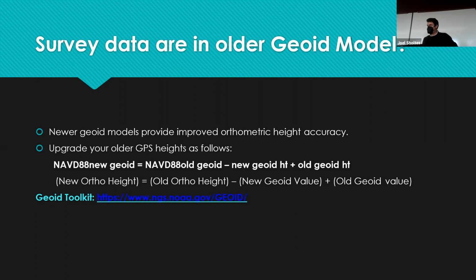There's a vertical datum, basically it's tied to mean sea level in Newfoundland. You remember that? And then they took that mean sea level of Newfoundland and basically spread this system of leveling all the way across the continental US. That's what it's based off of right now. We're going to get away from this, and it's all going to be satellite based next year.